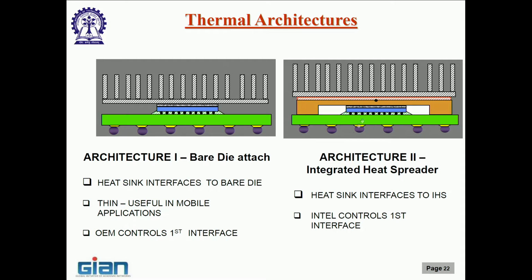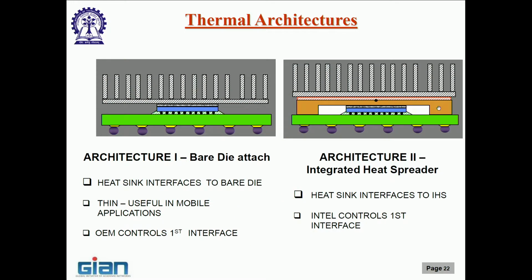Now, there is another architecture where you have the silicon and then, typically mostly copper, coated copper, a plate on top. You would have seen this yesterday when Professor Dasgupta was showing some pictures; you would have seen the word lid in many cases. It is also called lid, it is also called integrated heat spreader or IHS. Lid, why? Because it kind of protects the package, so that is one function.